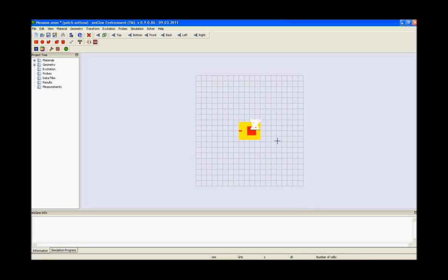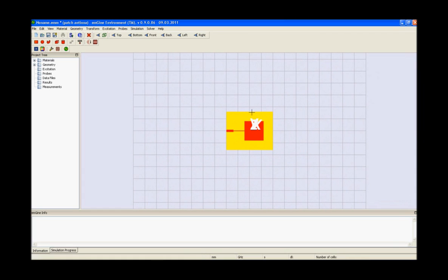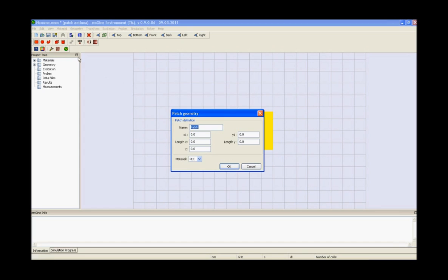The next step is to model the ground plane below the substrate. For the dimensions of ground plane below substrate, you should design a ground plane brick. The material setting of the brick must be changed to the desired ground plane. Because no material has yet been defined for the ground plane, you should select PEC as the material for the ground plane from the material drop-down list.